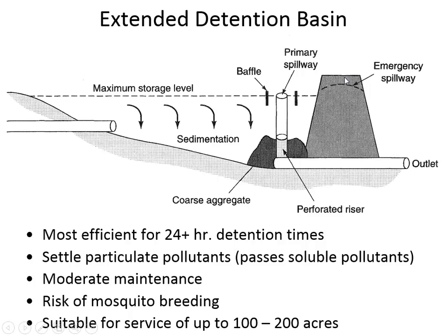Now, this is a cross-sectional view of a dam. The dam would probably have a low point somewhere, so that normally the water level is here, but if it rises even further, it would go over a part that maybe is more ruggedized. This low point is ruggedized compared to the rest of the dam, so that if water flows over it, it's not going to completely erode the structure.